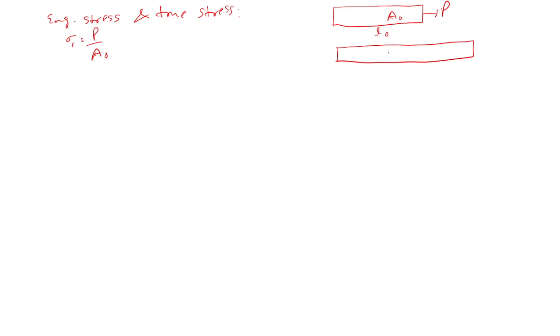That is okay. In engineering stress, you are saying sigma naught, it would be P by A naught. Let's suppose this is our initial length L naught, and P we applied, and its area is A naught. After the application of load it became like this, with A f, L f and P, right? So engineering stress would be this, and true stress would be P by A f, right? So in strength of materials we go for this only. Why? This is the question.